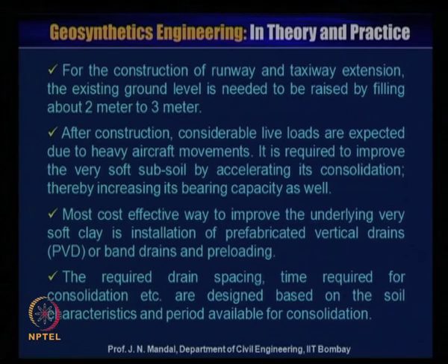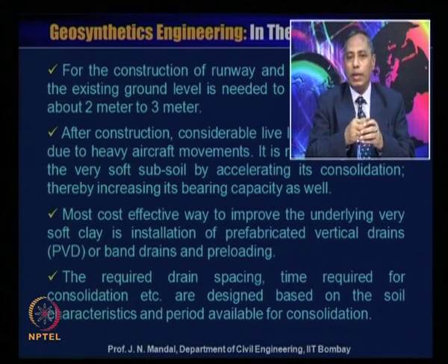For the construction of the runway and taxiway extension, the existing ground level needs to be raised by filling about 2 meter to 3 meter. After construction, considerable live load is expected due to the heavy aircraft movement. It is required to improve the very soft subsoil by accelerating its consolidation, thereby increasing its bearing capacity as well.